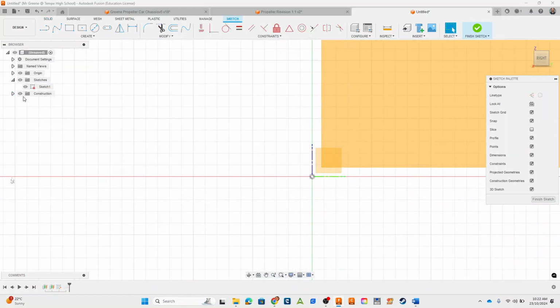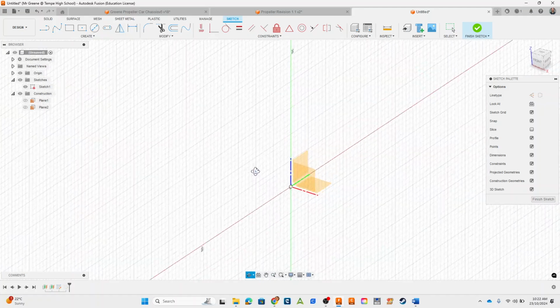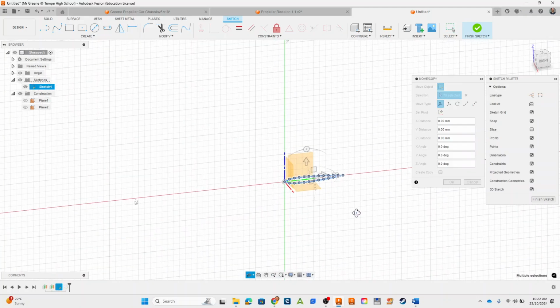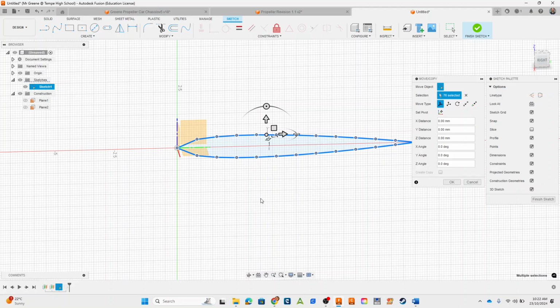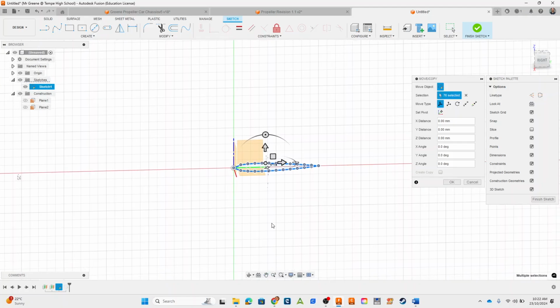Okay, and I'm going to start by pasting this down to my first plane. So my first construction plane is here. So what I'm going to do straight up is go Control V, paste, and that will put down that sketch for me, okay? I don't necessarily know the size of it just yet, but I'll put in that bounding box, the construction box, to size it properly, okay?